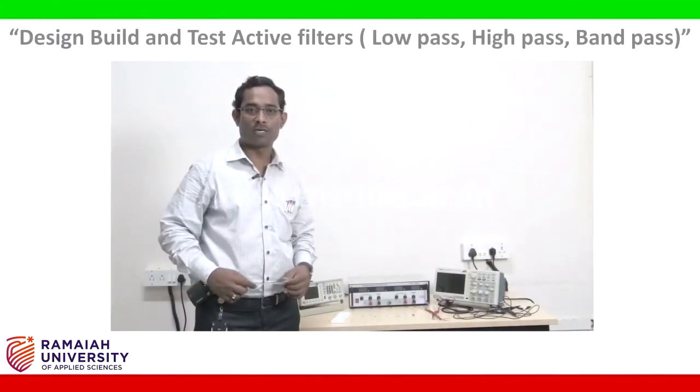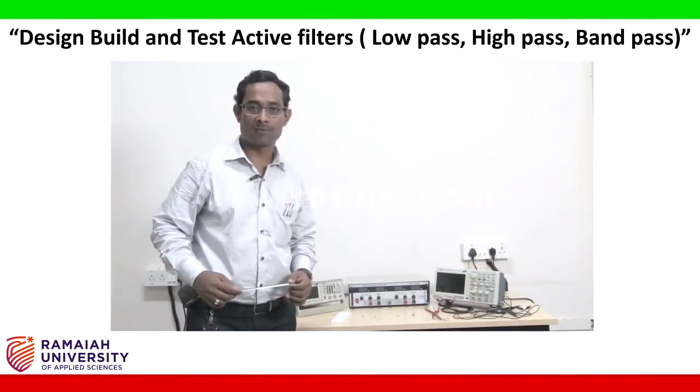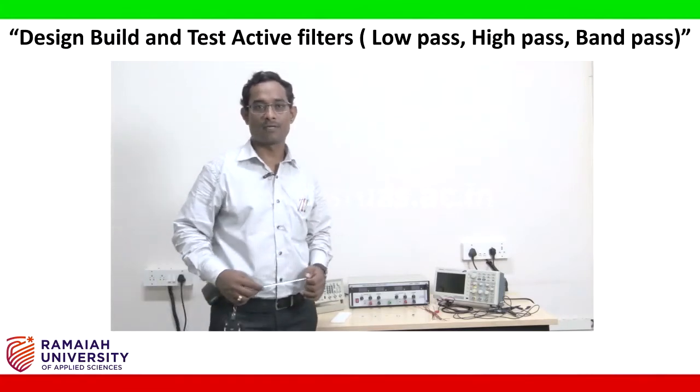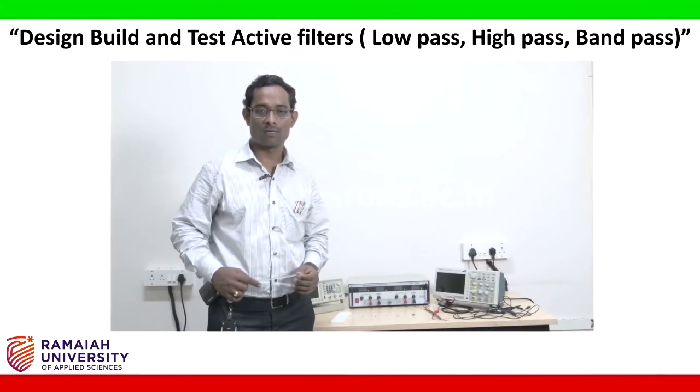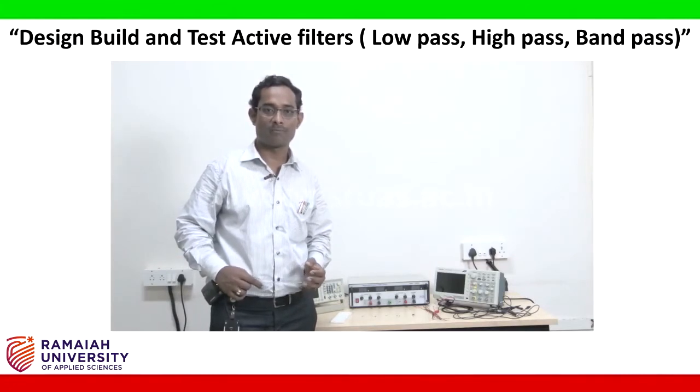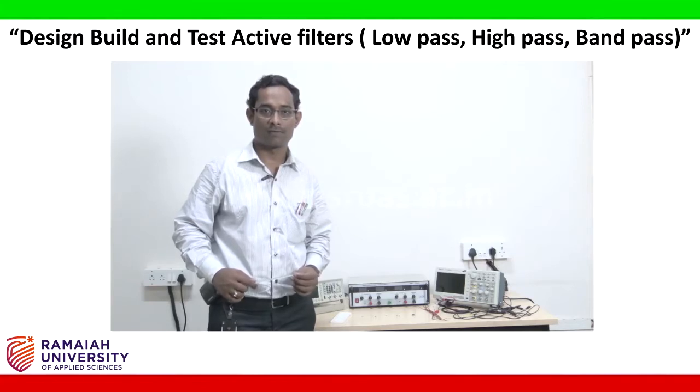Dear students, today I am going to teach the experiment of the active filter design. In that active filter design we have 3 filters: low pass filter, high pass filter and band pass filter. First I am going to teach the low pass filter. The aim of the experiment is to design a low pass filter for 1 kHz cutoff frequency.